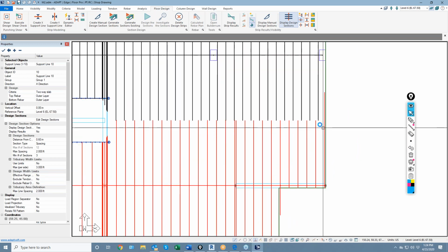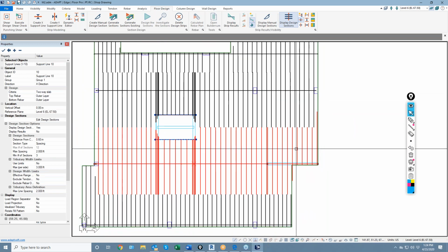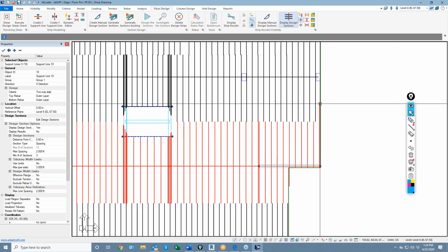This one, you can see this section right there, that could be detrimental, especially if this is a banded direction and you have one section that's quite a bit longer than the other sections, because the program uses the section geometry to determine the force that it maps. In this case, this section here has this cutout in the slab, so this is roughly equal or less than these larger sections.